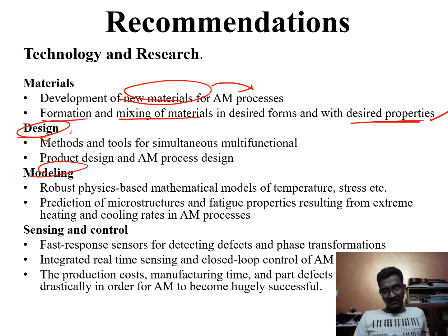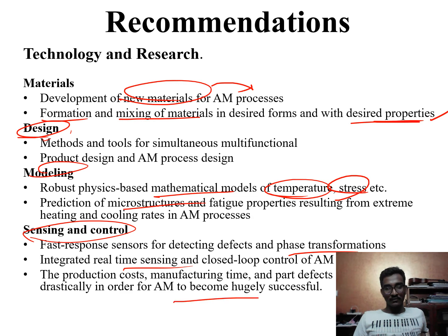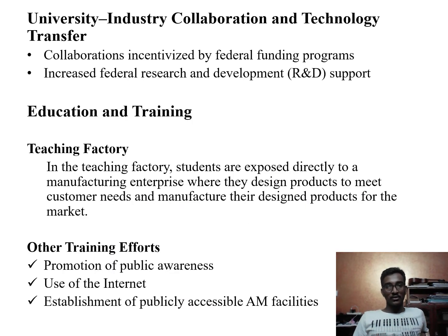So modeling is also required, robust physics-based mathematical models of temperature and stress, so that we can get the prediction of microstructure and fatigue properties resulting from the extreme heating and cooling rates. And finally, sensing and controlling. So fast response sensors for detecting defects and phase transformations, integrated real-time sensing and closed loop control, and then additive manufacturing becomes hugely successful. So these are a few collaborations, teaching factors and things.